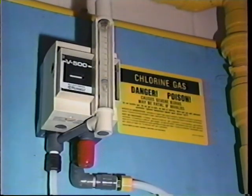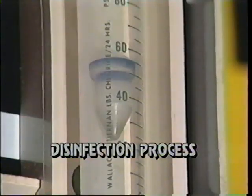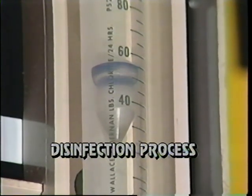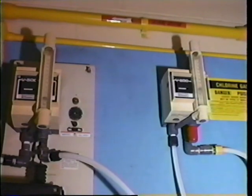Before the treated wastewater can be discharged into a receiving stream, it must be disinfected. Disinfection kills only the harmful pathogenic organisms as opposed to sterilization, which kills all organisms. Sterilization of the effluent is not a function of the treatment plant. A chlorine solution is mixed with the effluent from the secondary or tertiary clarifiers, and the mixture is diverted to a chlorine contact basin or tank.